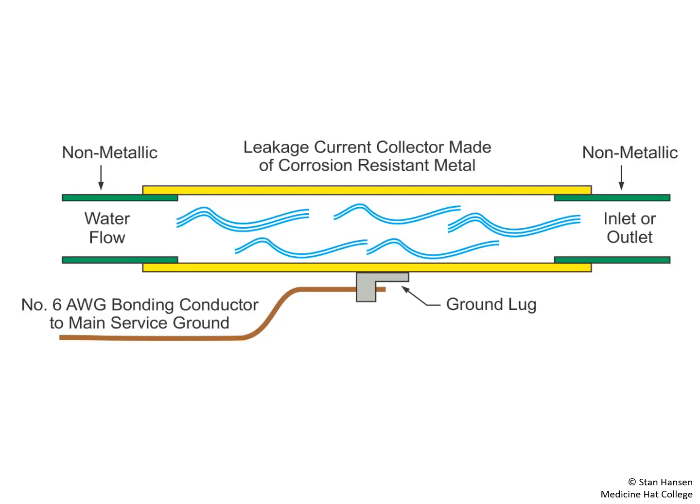If our spa or our hot tub is field assembled, we have to look at Rule 68-406, which talks about leakage current collectors. The job of a leakage current collector is to catch any residual electrical fields that might be found inside the water and give them a reasonable path to ground. This only applies to systems if the pump motor is not indicated as an insulated wet end pump.